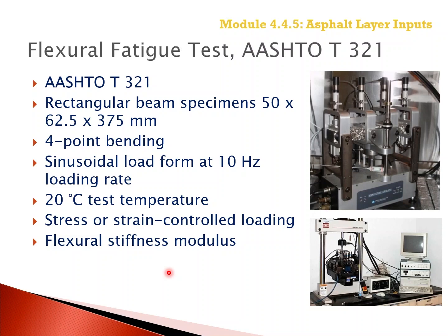This slide summarizes testing conditions of the bending beam fatigue test. The testing of one beam specimen is conducted at one temperature and one strain level. Multiple beam specimens are tested at different temperatures and different strain levels. A flexural fatigue test apparatus is also shown on the slide.